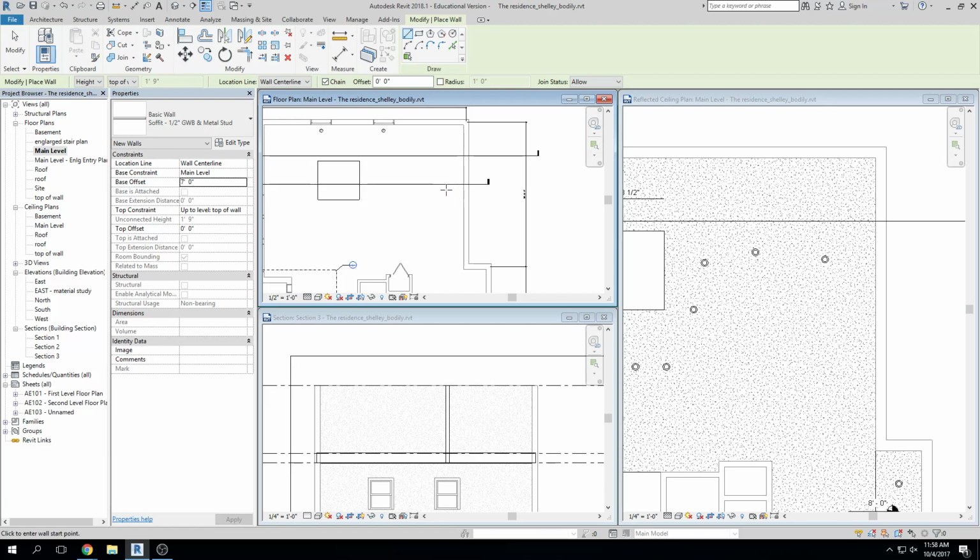And again, I say this a lot, and I say it because I think AutoCAD is different. When you're working in AutoCAD, you try and get everything correct the first time you do it, right? So you want the walls the right dimensions, you want them in the right place, and it's really easy to do that. In Revit, I generally will work and get things in the right general spot and then move it into the right place, and it just kind of works out that way.